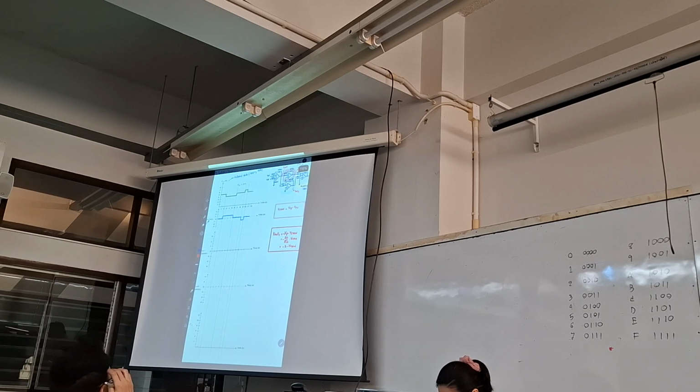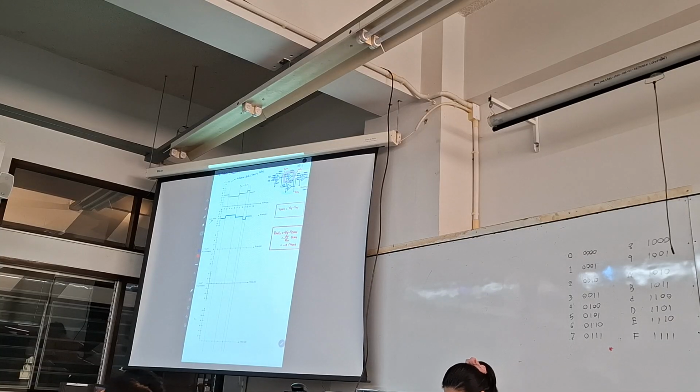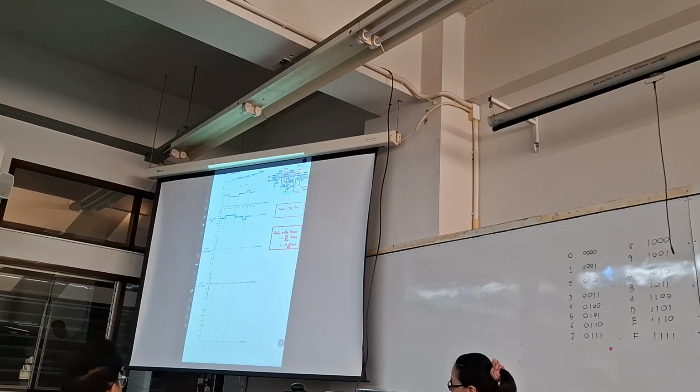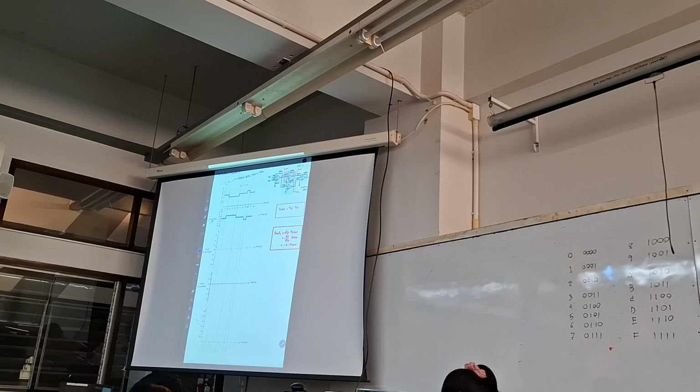Try to evaluate V out. V1 is equal to minus 3 multiplied with V error. So you have to use minus 3 times V error here. V error in the first section here is 0, so you have 0 multiplied with minus 3. Then output will equal to 0.